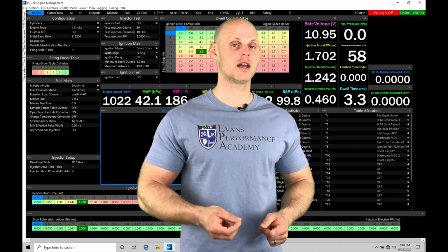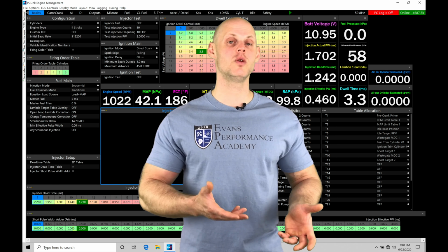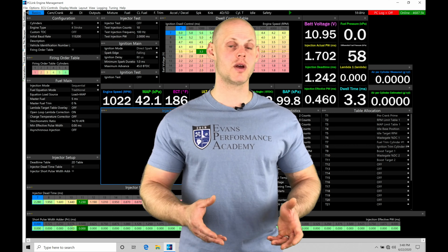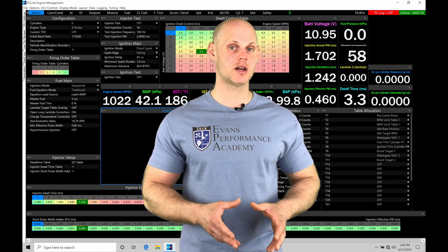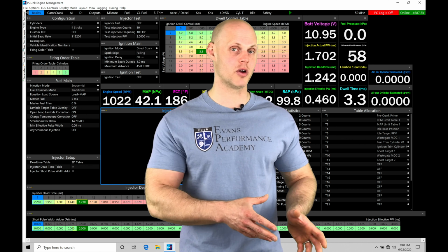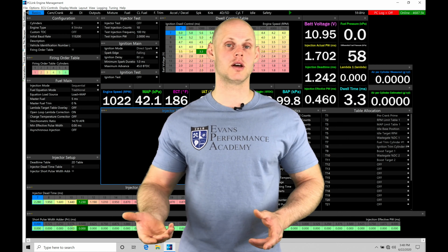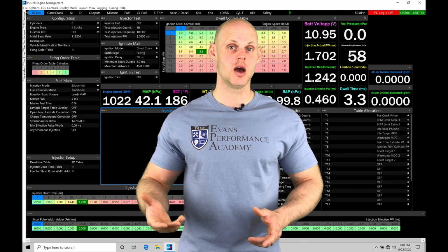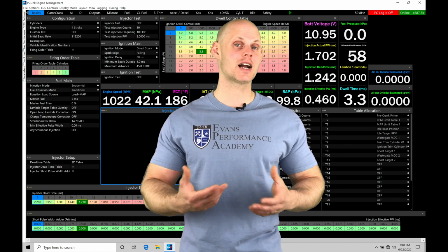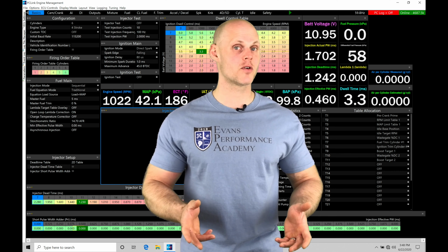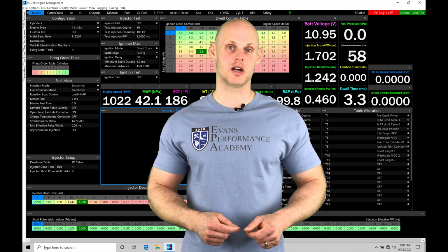We're also going to be taking a look at how to properly integrate the fuel and spark timing calculations so that we have a fuel table and then a spark timing table associated with our low cam operation, and a fuel and spark timing associated with our high cam operation. We'll find this is exactly what Honda's done in the programming in the factory ECUs. We're going to be mimicking that and learning how to integrate that into our calibration process. Without further wait, let's jump into our video so we can check this out.